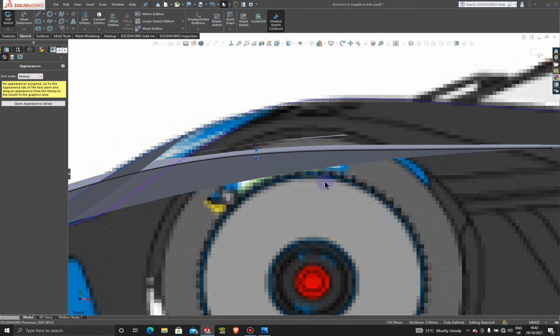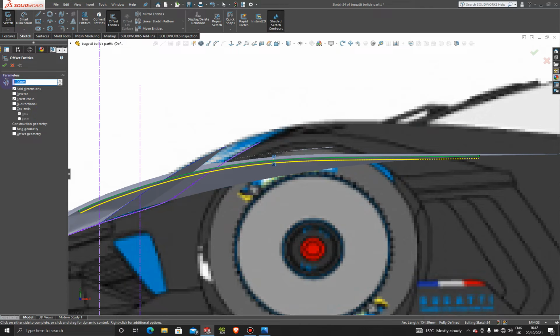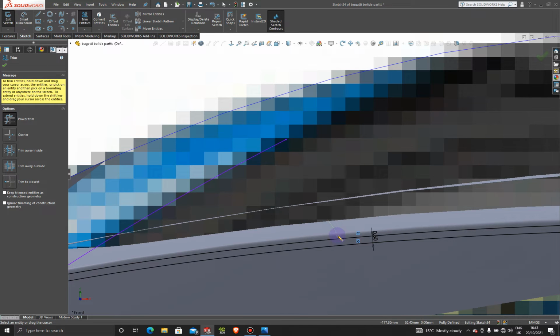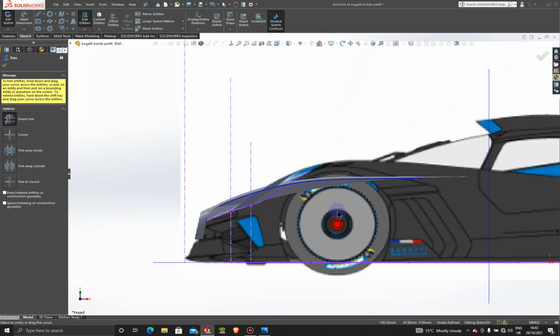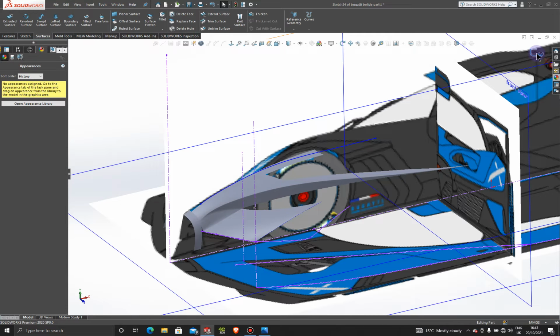All right, so now that is anchored, and I think it's long enough as well. It's not on level with that one, it doesn't need to be, but it needs to be a little bit lower. So I want to add a little offset on this sketch here, and I want to try 0.5. Okay, and then we're going to cut the top one. So that's going to be enough drop. If not, we can always adjust it. So exit the sketch.